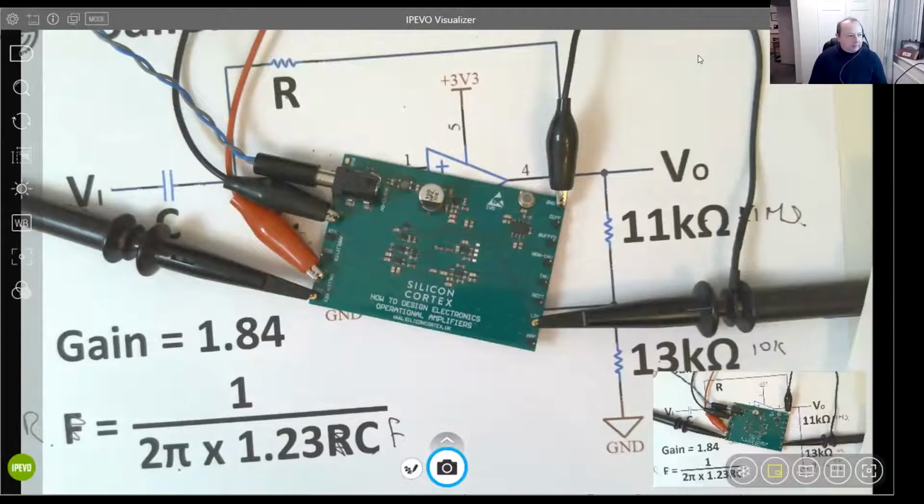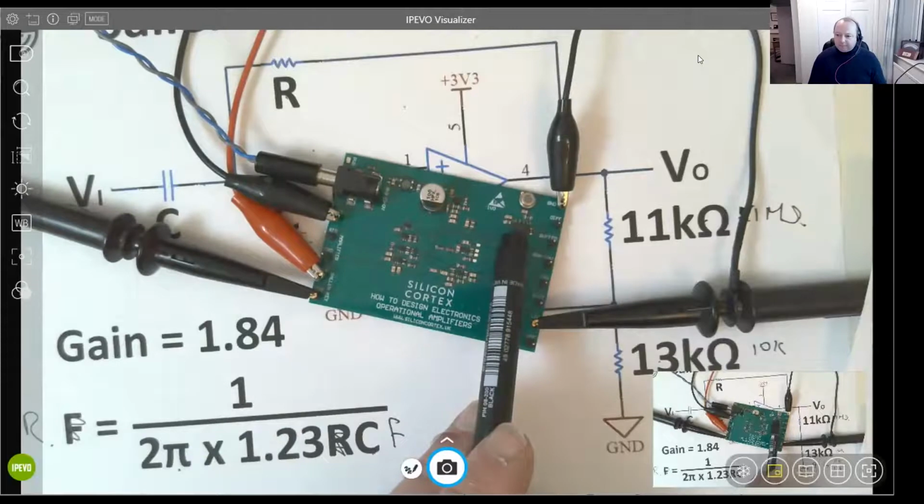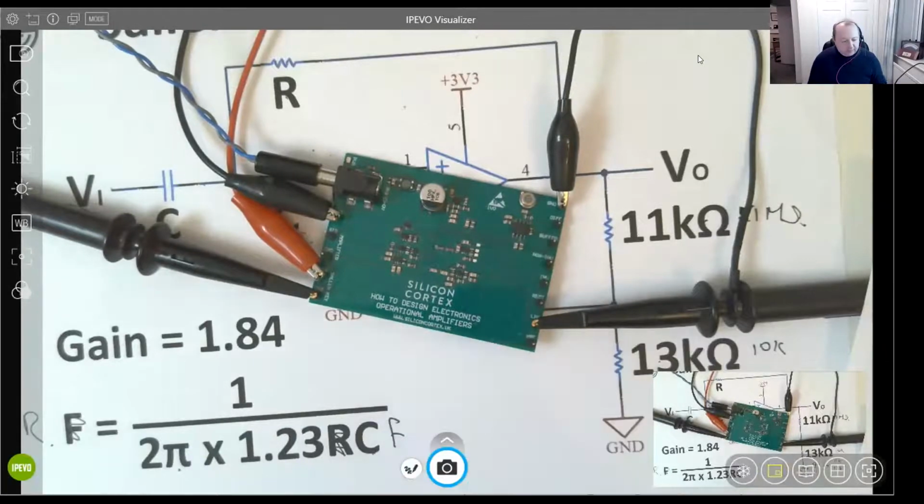I think the way to solve inefficiency, which is heat, is, if it's high power, you just slam the power on or slam the power off, so you don't end up having voltage drop inside the devices, because that's how the inefficiency happens. But I think D-class amplifiers are the only ones you've got to be careful of, which of course I haven't covered here.